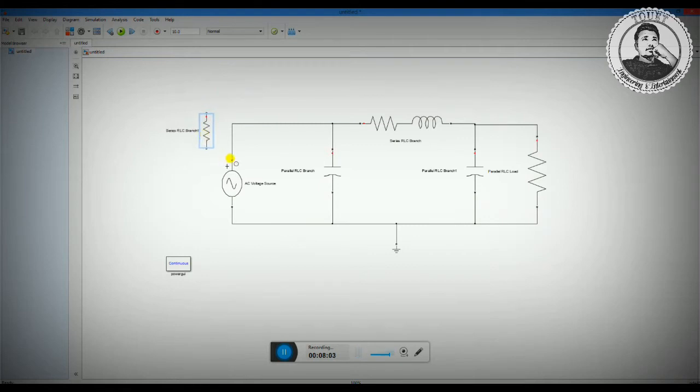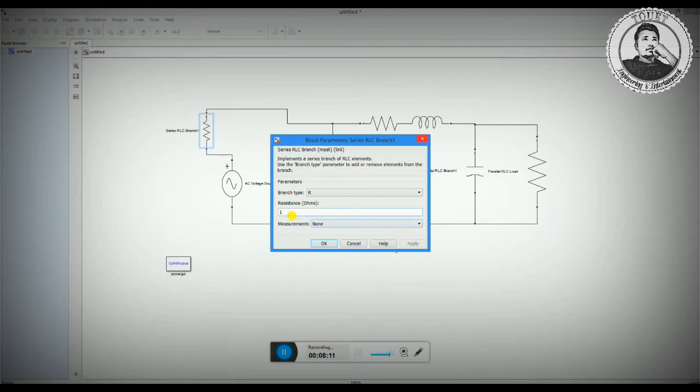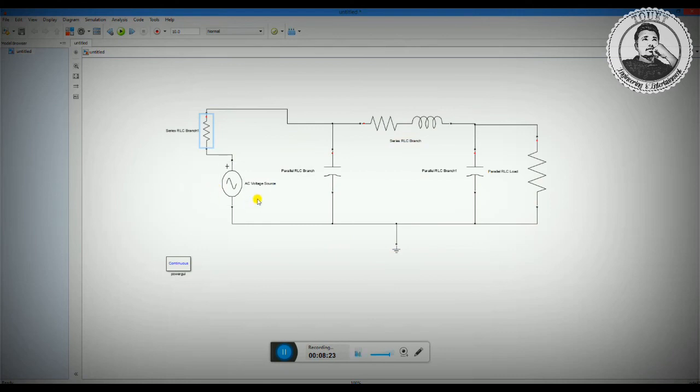voltage source. So break the wire from here, connect from here, and join it from here, and decrease the value to as minimum as possible. So I have taken 0.01, in micro you can say. Now run it. I guess it will be okay now.